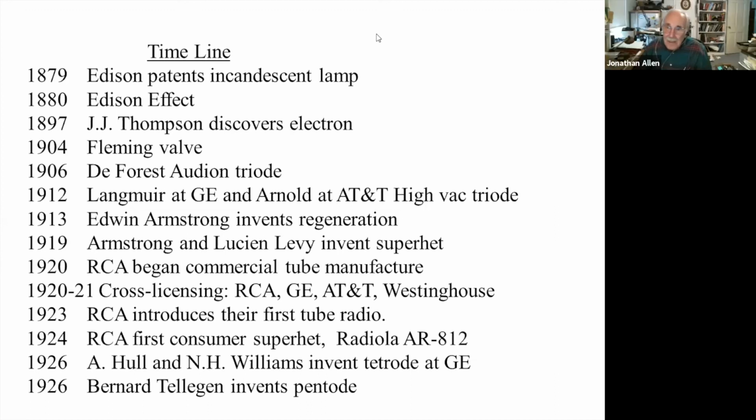Well, the beam tetrode is a tube where, instead of using a suppressor grid, you form the electrons into a collimated beam, which essentially drives the electrons back to the plate. It avoids that problem. And for really high power, the beam tetrode is, in fact, a preferred tube.